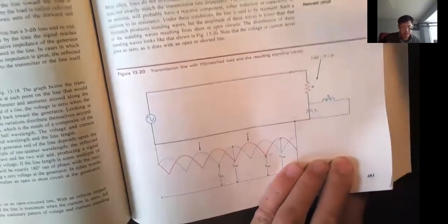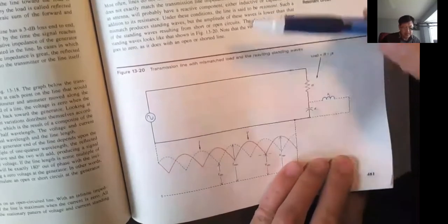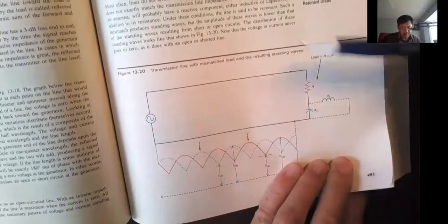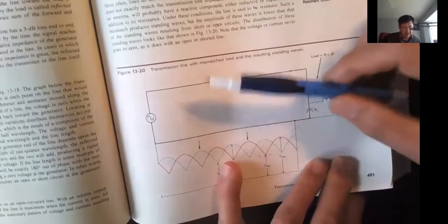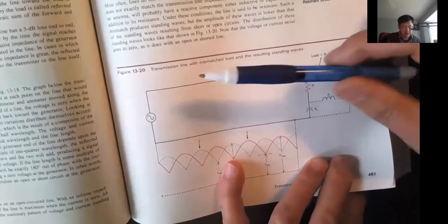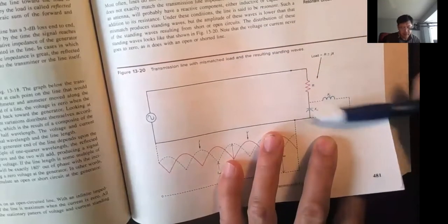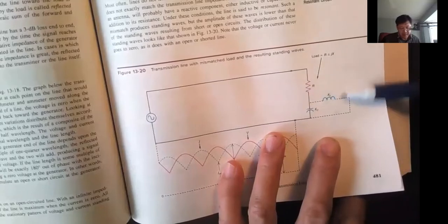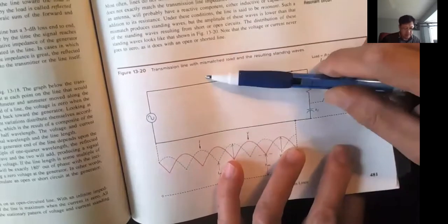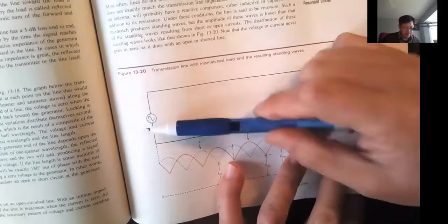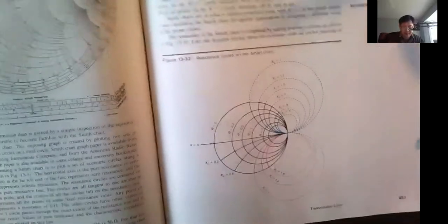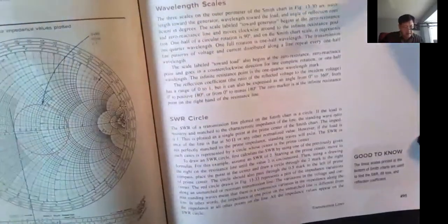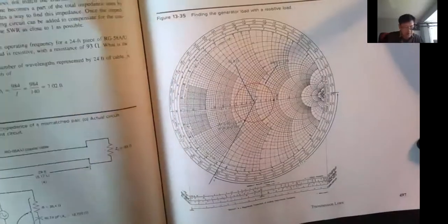Because in the old days, we had just two components when we analyzed circuits, source and load. Now we have to take care of the transmission line. There is a third component. So the Smith chart is basically how we can quickly estimate the combined impedance of the load plus the transmission line to the source, and that can be very handy. Let's do an example.